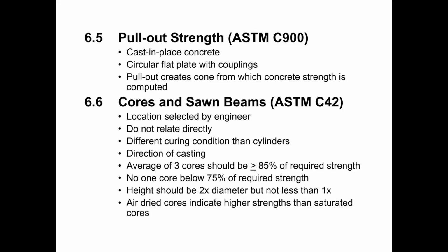When we want to test the strength, we have a device that threads into that collar on the plate that's in the concrete. That device has a load gauge on it, and so we start cranking that gauge and shearing the steel plate out of the surface of the concrete. And based on the amount of force that's needed to pull the plate out of the concrete, we can then estimate the compressive strength.